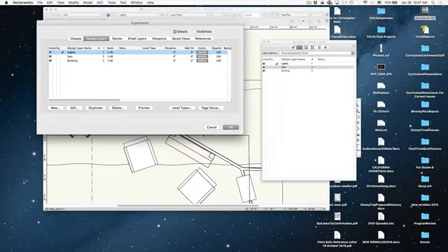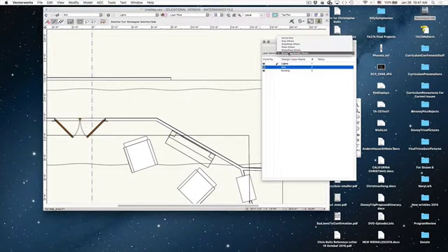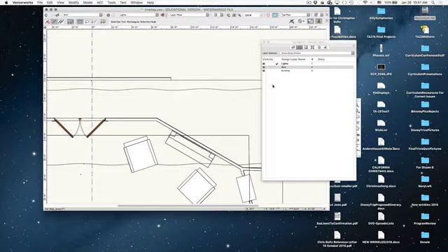When I'm over in layers, I have the exact same list. Active, gray, show. Here is where I am very big on show others or show snap others, because now I don't want to edit the building. If I'm working on lighting, I don't want to edit the scenery, right? That's not my job. Of course, editing the building is really not my job, because as the designer, if I say, oh, I'm going to knock a hole in the building, do you think the production's going to do that for you?